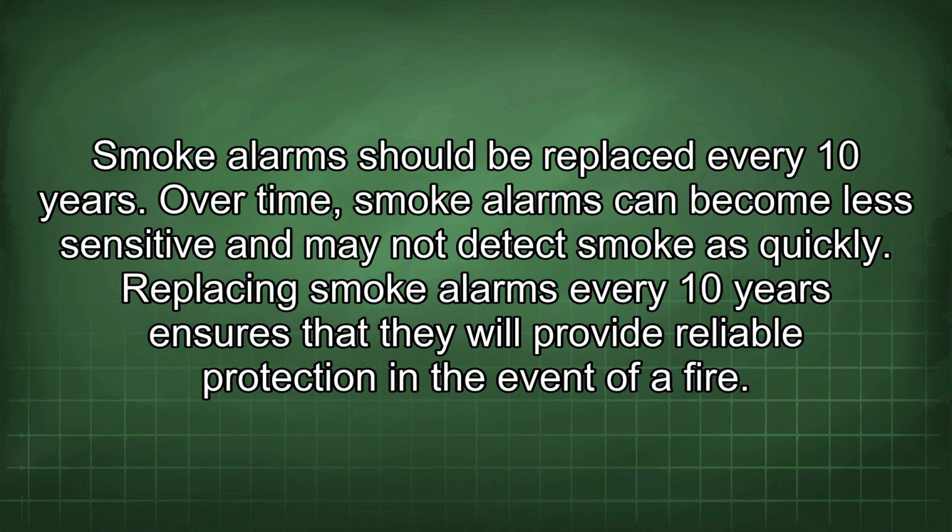Smoke alarms should be replaced every 10 years. Over time, smoke alarms can become less sensitive and may not detect smoke as quickly. Replacing smoke alarms every 10 years ensures that they will provide reliable protection in the event of a fire.